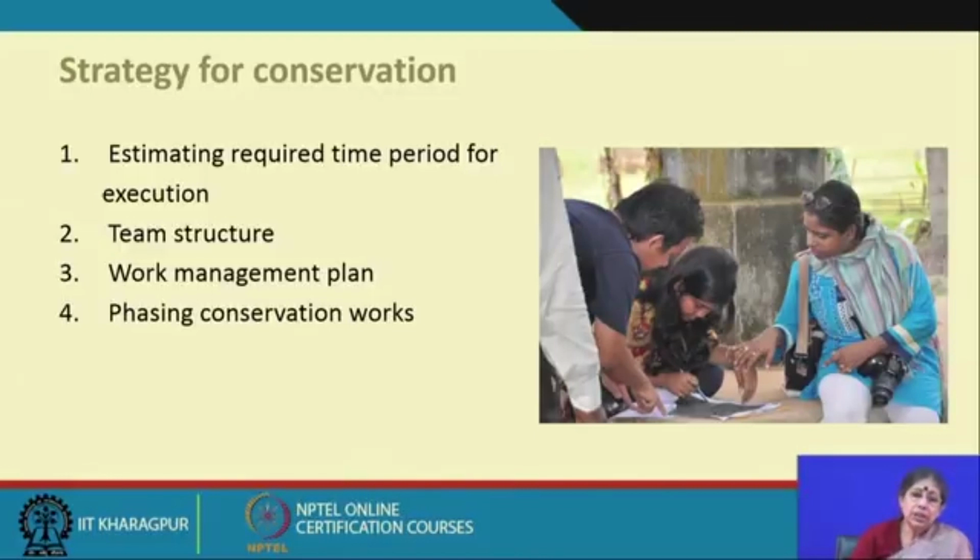So, these are very preliminary ideas about how the documentation process will go on. First is your understanding of the measure drawing, which will make a basis for that, and the different parts have to be documented, and on the measure drawing one has to do the problem identification and also give suggestions about what further investigation is required. The preliminary investigation report and the further investigation record are an ongoing process, and then come the immediate measure, intermediate measure, and the long term process, and then the condition mapping, which is very, very important and has to be done very accurately with proper expertise.